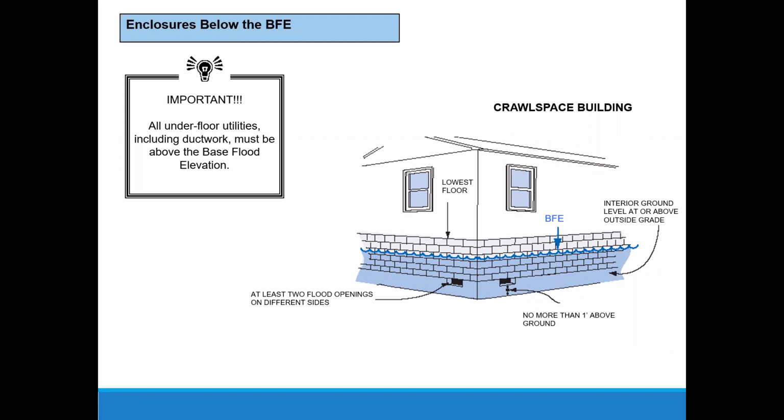The ductwork that is often found in the crawl space area would also have to be elevated above the base flood elevation. And we have had issues where, after a flood, companies will come out and offer to clean ductwork. At that point, they used a steamer to try to clean it, and so they were just introducing more moisture to these areas.